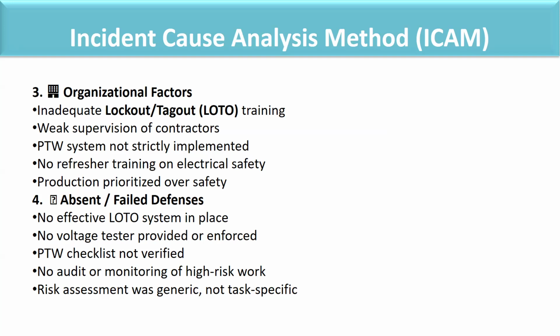PTW system not strictly implemented. It was just for the formalities. No refresher training on electrical safety. So the person who was there was not provided refresher training. Production prioritized over safety. So they compromise safety for production.